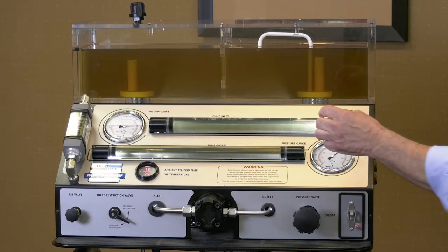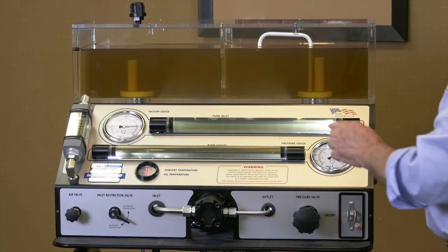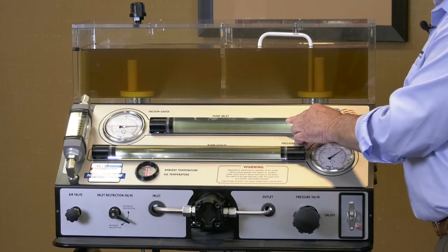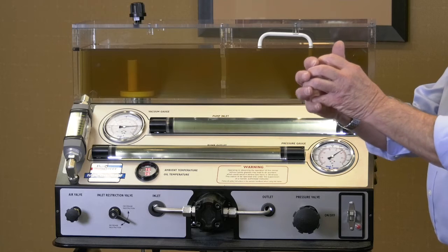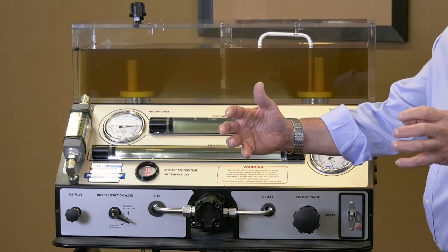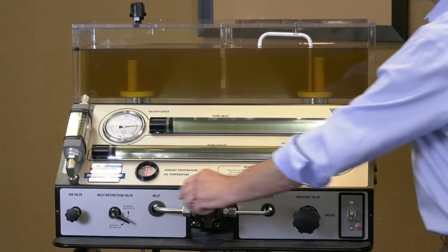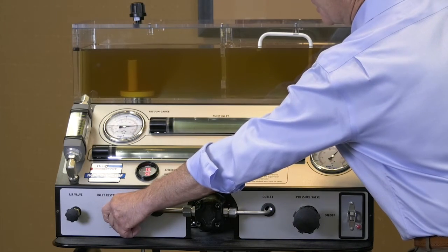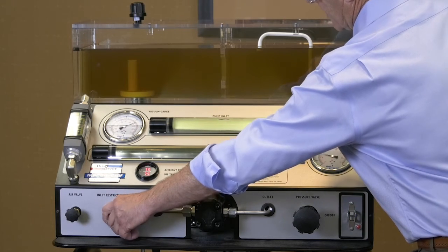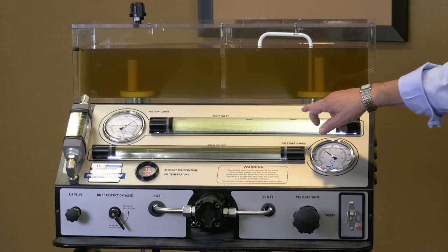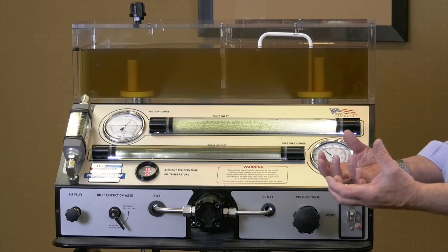We'll get to a point where you will see the dissolved air coming out of the oil on the inlet side of the pump. In other words, in a nutshell, I'm going to take the pressure off the oil. The dissolved air is going to obviously come out of the oil. So here we go. As I increase resistance on the inlet side of the pump here, I can see the dissolved air has come out of the oil.